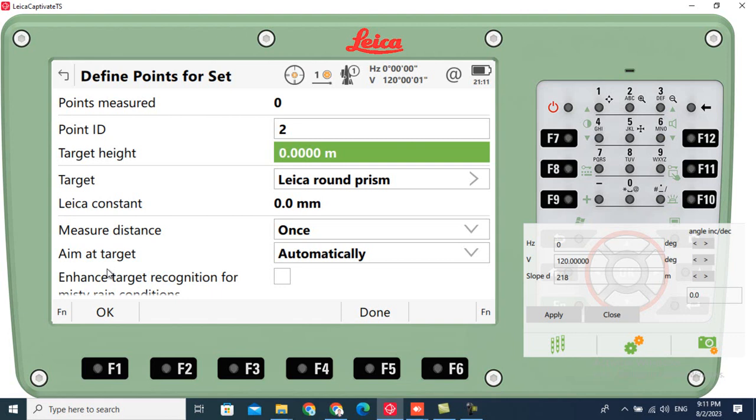Okay. The reason I say that is because sometimes I'm measuring, I know I should probably be using a prism, but if I am measuring reflectorless, what would be the option? I should manually centralize it myself. That would be the option. You will do it yourself, manually. You will center to these targets by yourself. This application we can use it. And in this case, do I go for the option manual or what do I do?